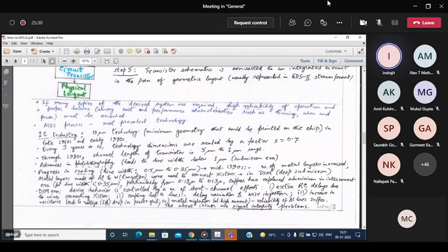Due to non-uniform width of the current conducting wires, at some point of time, due to high current, as metal ions migrate, it can result in a void or discontinuity in the middle of a wire. Then the signal cannot flow to the desired destination, right? This is just an example of an undesirable effect of the relentless downscaling of sizes.